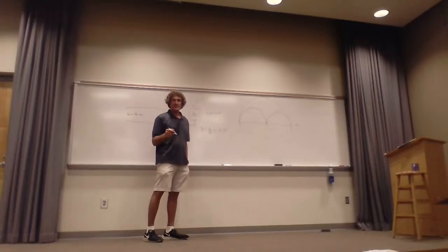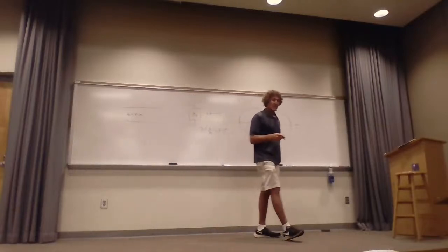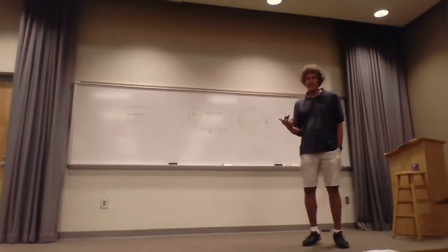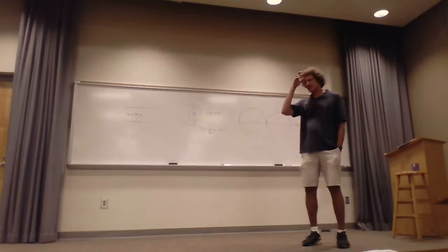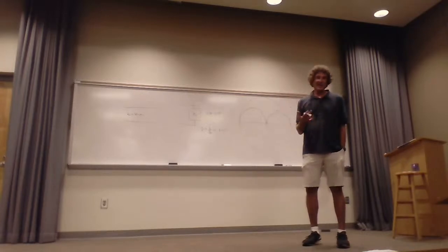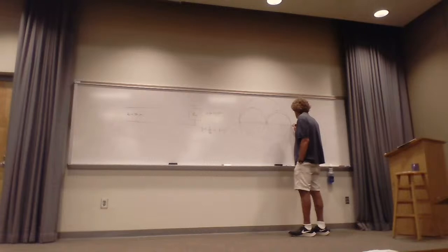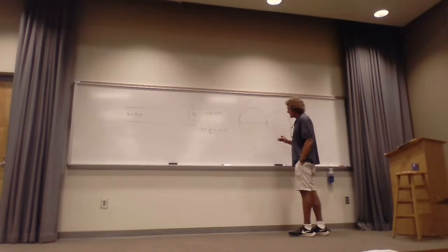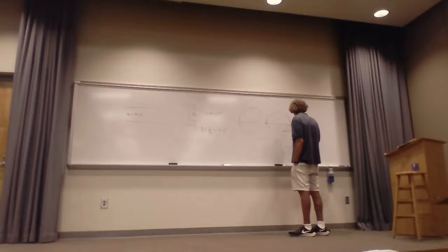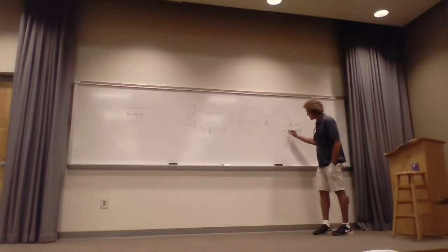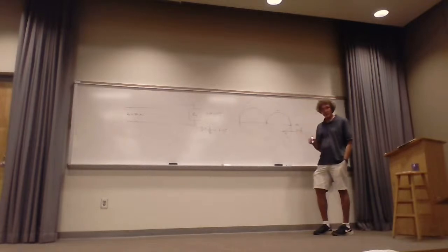Now you can see that that's inside the one circle, right? Whenever the real part's less than 1, you're inside the one circle, correct, class? Or I should say the real part is greater than 1, my bad, greater than 1. So here 5 is somewhere like this. You look up, it's about there, right? And then I got minus J5. Well, minus J5 is here, so the point is somewhere in here. This is going to be 5 minus J5, right? That would be the first point, and that's ZL. Y'all agree with that?